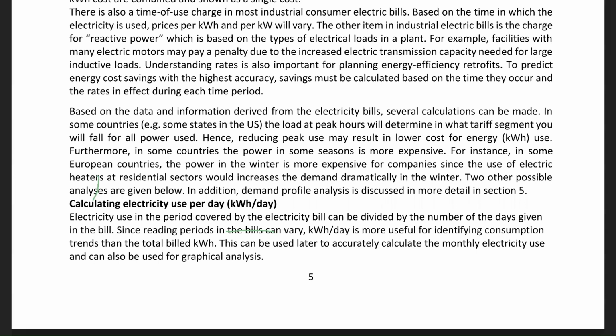For example, for a multi-story 2 BHK house with a three-phase connection, which phase connection it is also matters. If the declaration is that 6 kilowatt is the contract load, that is the load that we will use, 6 kilowatt or less. That factor is also taken while calculating the tariffs, and it is mentioned in the electricity bill.